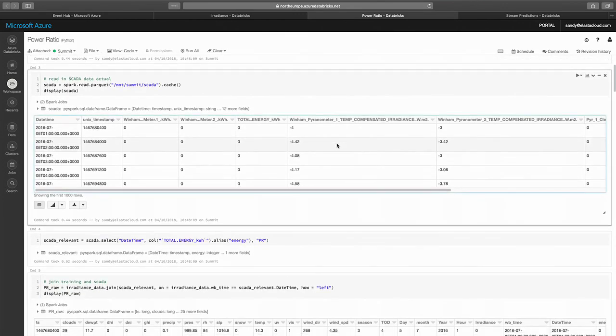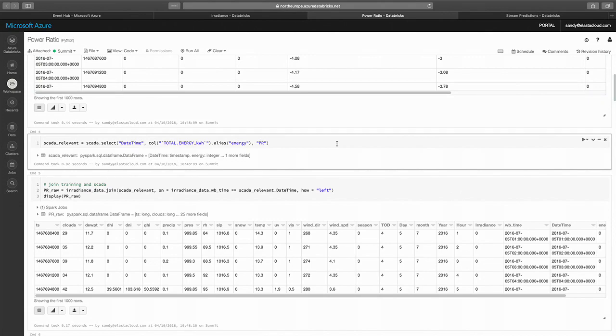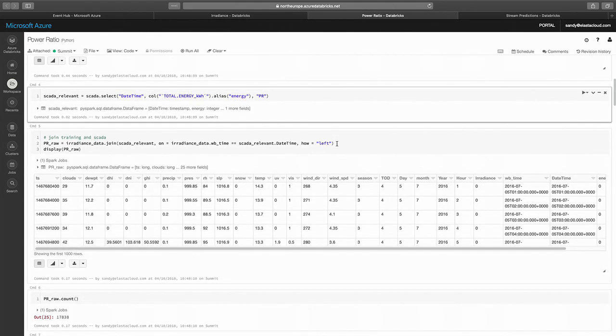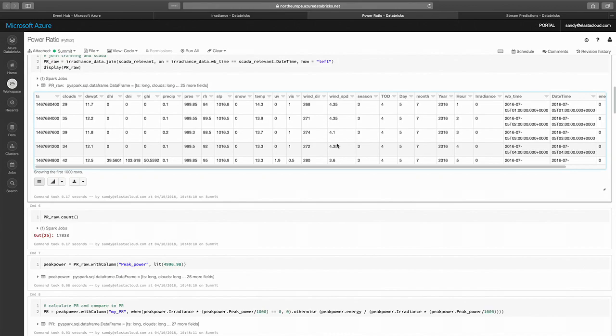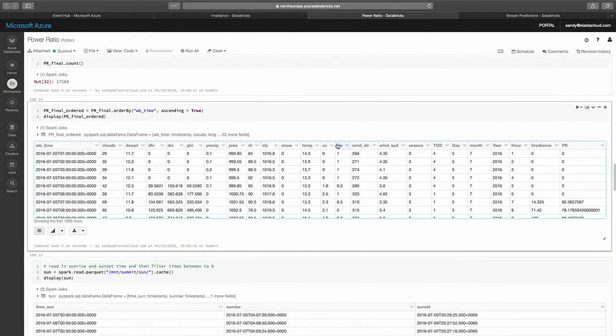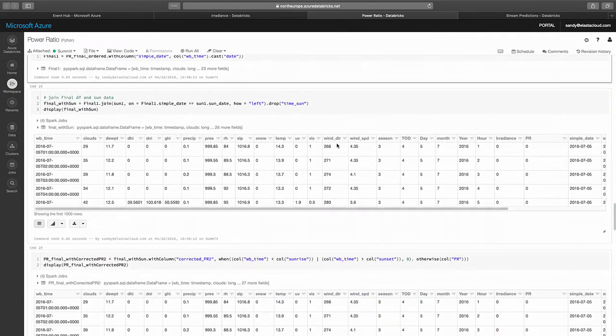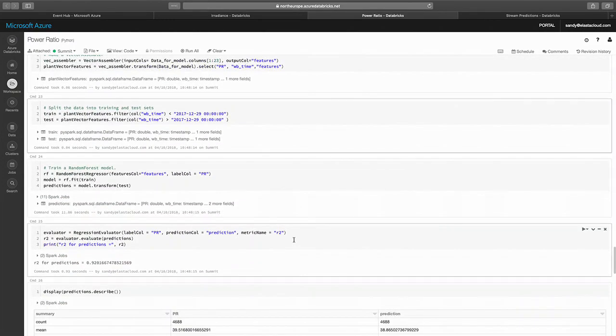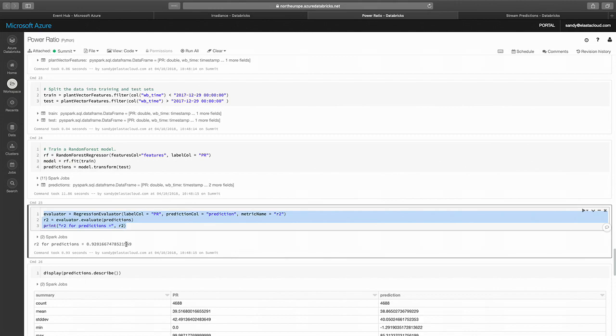Now we've changed that, and we have a random forest model based on all of the conditions we know around solar farms. So we start to think about power as well as just irradiation. We use the same feature sets across both of them, and this model runs secondly after our radiation model, using a random forest here. For this, we now get 92% accuracy, and this isn't just predicting percentage power at a certain time, this is predicting actual power coming out of the plant. So it's given us a massive boost in terms of what we're doing. This is about 92% again in dev test, and then in production, I think we get about 87% at the minute. So it's been a big change to us.